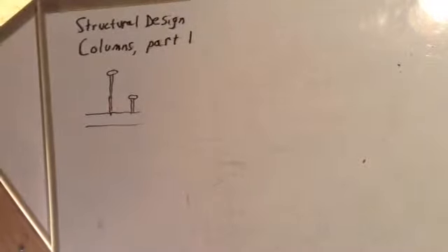The strength of a column isn't necessarily related to the strength of the column material. The column strength is more related to the stiffness of the column material. An example of this concept can be seen by comparing carbon steel, which is cheap steel, to stainless steel. That's the pricey steel. The carbon steel has a greater modulus of elasticity. It's not much greater, but it is slightly greater, which means it's a little stiffer than that of stainless steel. But stainless steel can withstand more stress. It can take more pounds per square inch.